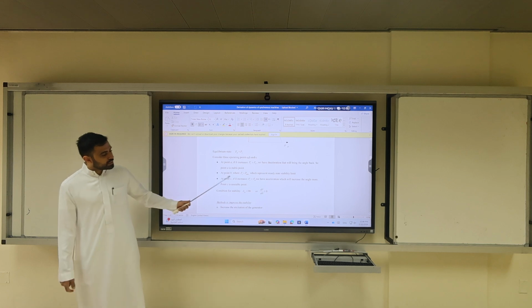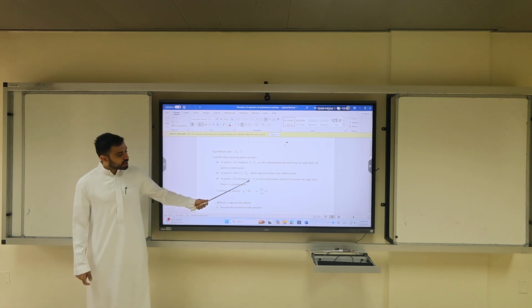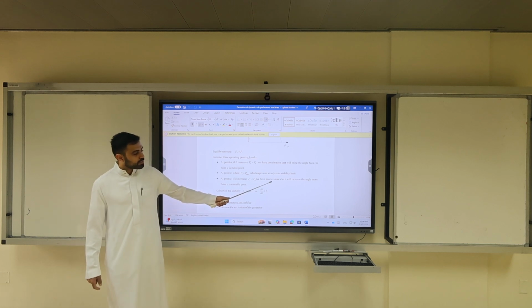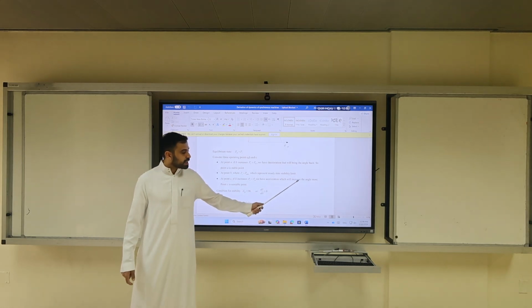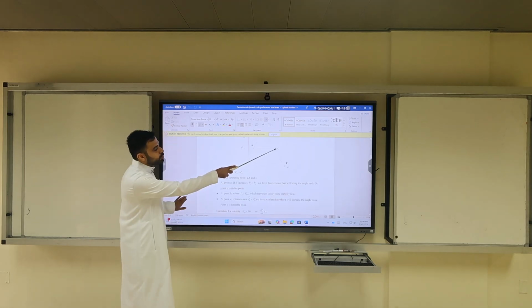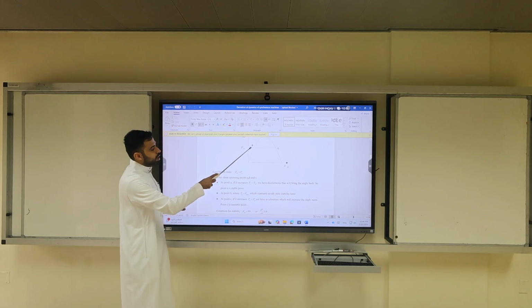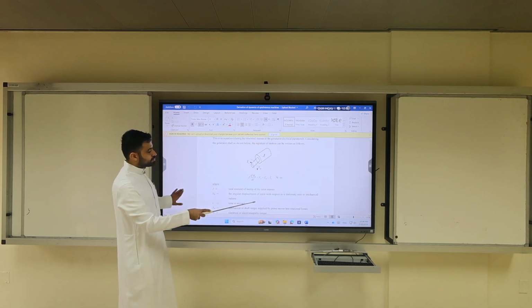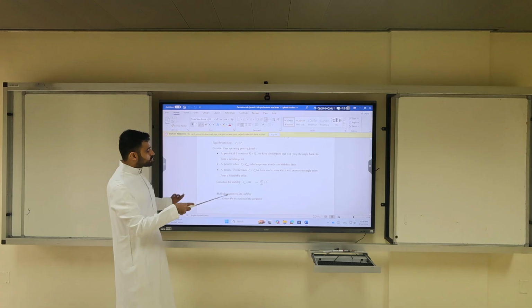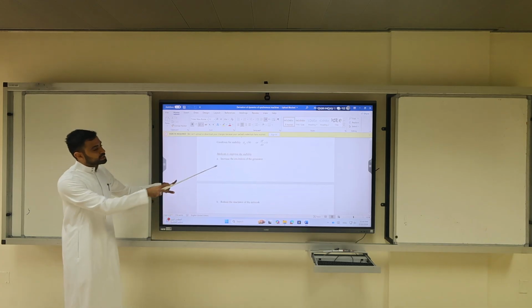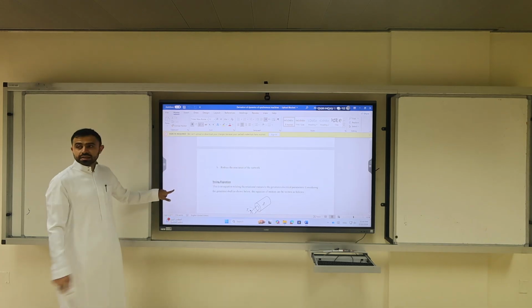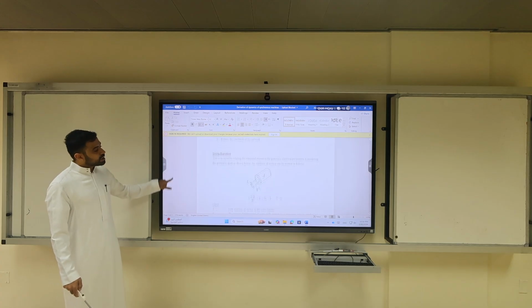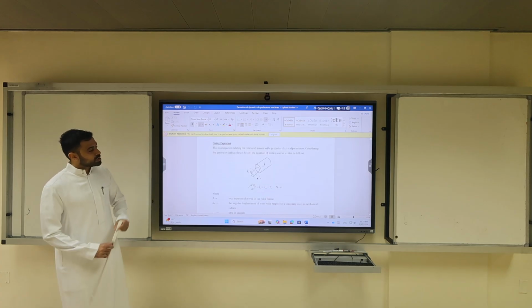At point C, if delta increases, P mechanical will be greater than electrical, and we will have acceleration which will increase the angle. At point C, we will move away from stability. While at angle A, if we increase delta, your equation would bring it back, okay? So methods to improve stability: increase excitation voltage, reduce reluctance of the network. What other thing we have? We have the swing equation.